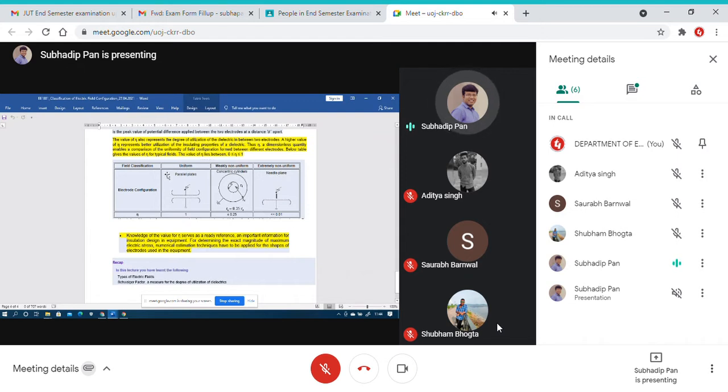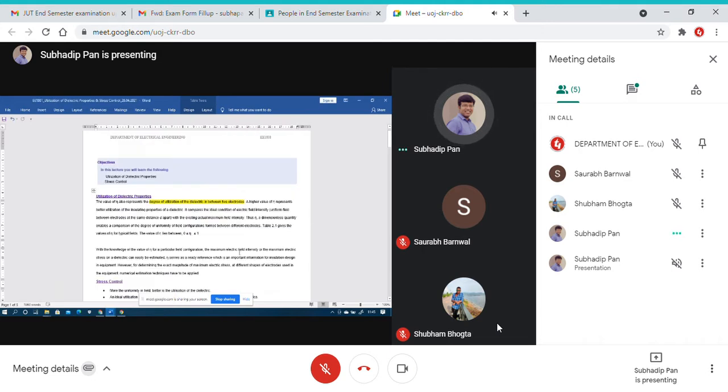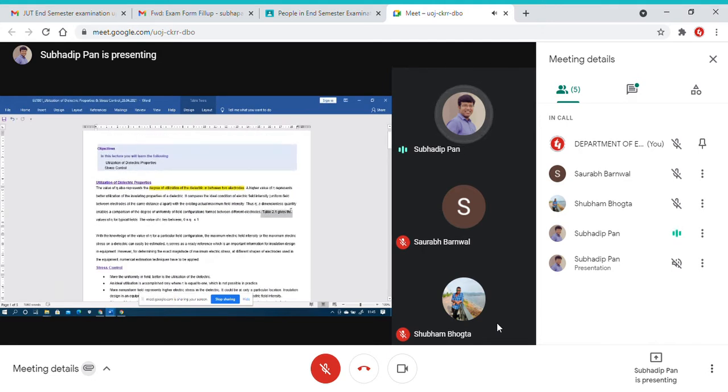So for the parallel plates, mu is always equal to 1. For the cylindrical structures, which have a weakly non-uniform field, mu will be less than 0.25, and then there is the extremely non-uniform field. In case of an extremely non-uniform field, the electrode configuration will be like needle to needle plates. For those cases, the factor will be very much less than 0.01. So from that table, Table 2.1 gives the value of mu for a typical field.